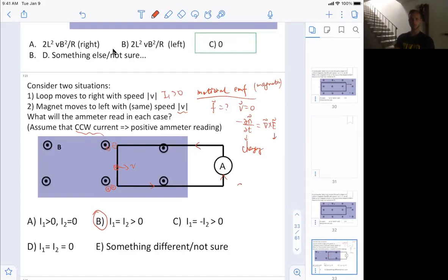But the beauty of Faraday's law is that no matter what your scenario is, you can always view this using the change in magnetic flux to explain it, and that is talked about in Lenz's law. So this negative sign represents the change. If your flux is increasing, then to oppose that change, you need to induce a current to produce a negative of that flux. So the induced flux has to be opposite to the flux that is increasing.